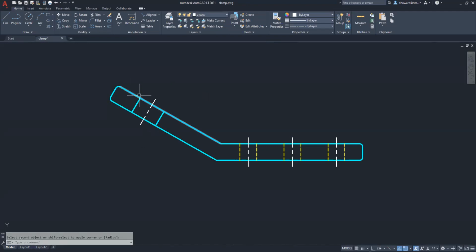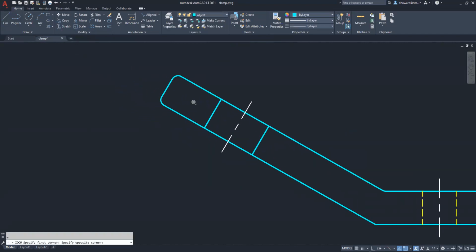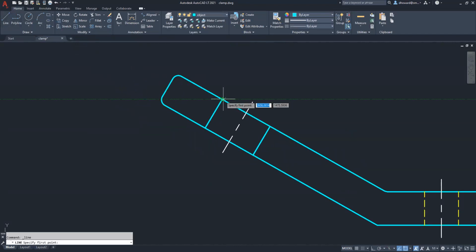And interestingly, this guy gets it too. So we'll have to make some sacrificial lines here. Oops. Going back to my object layer and make some sacrificial lines so we can do it here. You zoom in on that. So from the corner just to anywhere, I have my nearest snap on, so that's making it easy here.